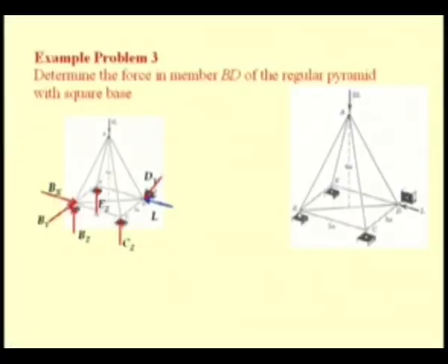But let us see this problem. Here we are just interested to find the force in the member BD. So, in order to determine the force in this member BD, we can either consider the equilibrium of this joint or the equilibrium of this joint, and the only criterion that has to be satisfied is that since in 3D from the force summation equations we can determine 3 unknowns, at a joint we should only have 3 unknown components of force to be determined.